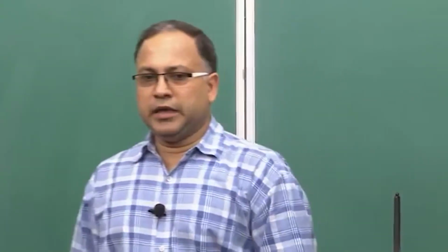Welcome back to the course Mechanics of Solids. In the last lecture, if you recall, we talked about strain and strain in the xy plane. If you know the strain components in the xy plane, you can find the strain components in any arbitrary coordinate system like x prime, y prime and so on. We developed the equations from which we could conclude that for strain also, very similar to the stress concept, you get the Mohr circle of strain, from where you get the strain components in some arbitrary coordinate system.